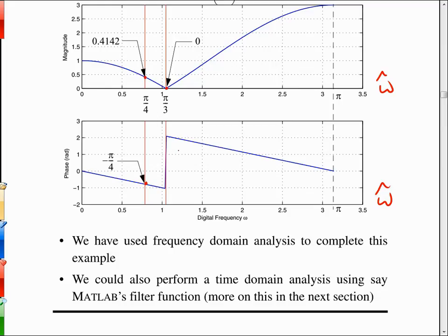But another really simple example of where it might be useful would be a single tone could be excised. A lot of times in audio processing, we get interference from the lights and basically the power line frequency. The power company generates our AC power at 60 cycles per second. So you all know what a 60 cycle hum or buzz sounds like. You've probably heard a PA system where you have that humming sound in the background and it's quite annoying. That stays pretty stationary, so you could notch that out, and if you're not caring about bass notes from bass instruments right at 60 hertz, maybe you're okay. If the bass guitar hits something right at 60 hertz, well, we won't hear it because it gets removed. But in most applications, it could be in a PA system or something.